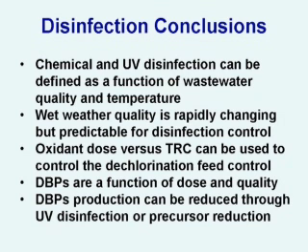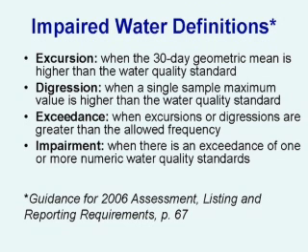This is data from Atlanta where we looked at disinfecting. The red line shows the dose that we would be putting in for disinfecting the raw CSO. The blue line is after the treatment process, and that process included filtration, knocking down the solids to about the 90% level. So at the beginning, if you were going to dose just the raw CSO itself, you're putting in about 4 times the chlorine in this case, and you could actually have about 10 times the precursors that could cause disinfection byproducts. So these are considerations you need to take when looking at disinfection, how you design it and how you control it.